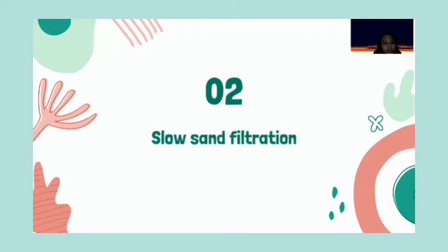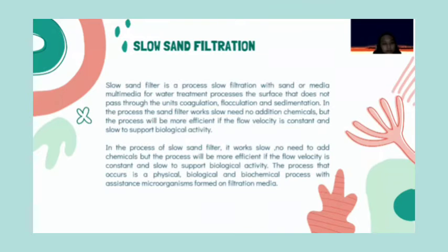Second is slow sand filtration. Slow sand filter is a slow filtration process with sand or multimedia for water treatment, but it does not pass through the flocculation and sedimentation units. In the process, the sand filter workflow needs no added chemicals, but the process will be more efficient if the flow velocity is constant and slow to support biological activity.